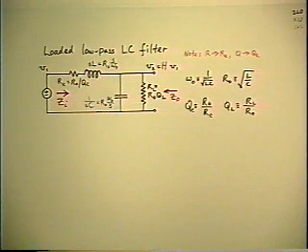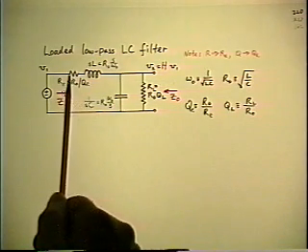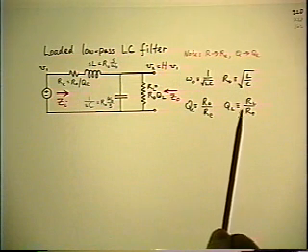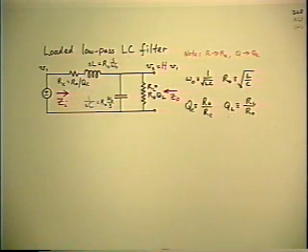And I do that on purpose, in order for the interpretation of the symbols to be consistent with historical usage. That is, Q factors were originally defined in terms of tank circuits, where high Q means low losses, low damping, and big peaks. This is the case for the QE. The QE goes to infinity if the RE goes to 0, which is the limiting case of 0 losses. We want to make the QL consistent with that. We want infinite Q to correspond to 0 damping.